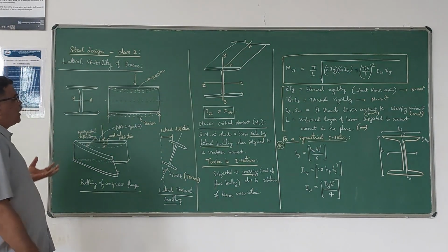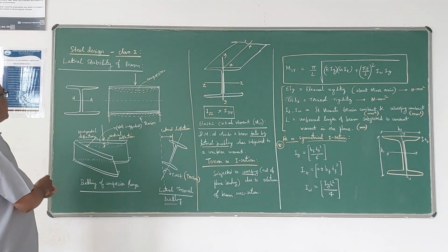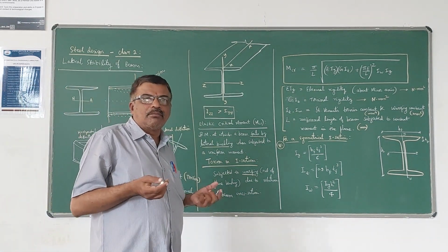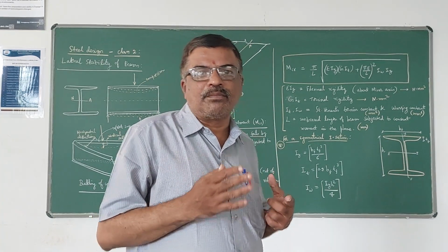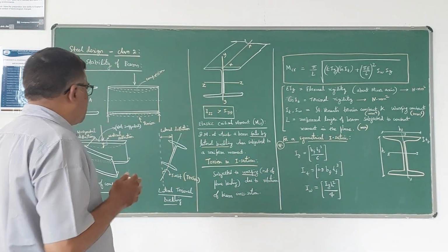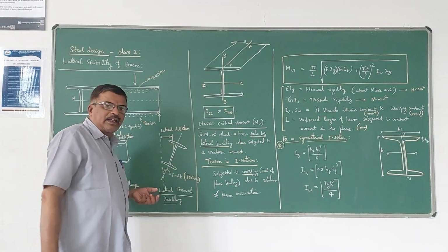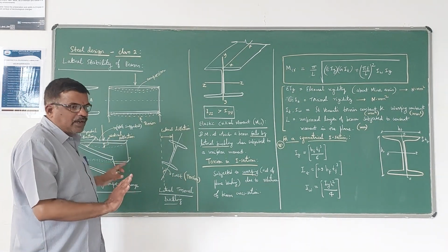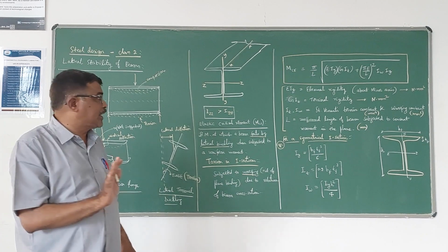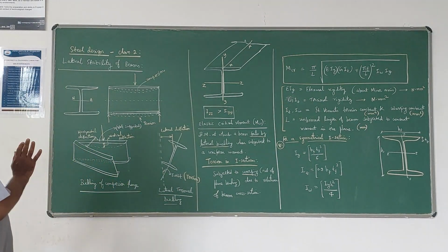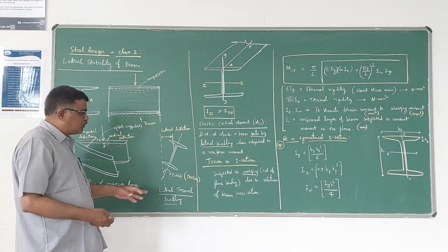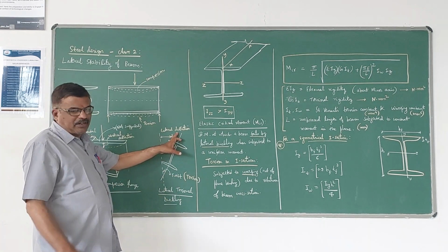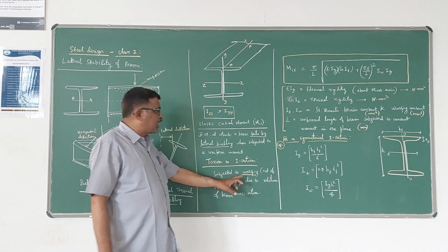So this is a simple concept of an unrestrained beam. Lateral stability of the beam can be achieved by supporting the compression flange of the beam, which I had explained in the earlier lecture. Here, what I mean to say is, when the beam is laterally unrestrained, it is subjected to both torsion as well as lateral deflection, and warping will take place.